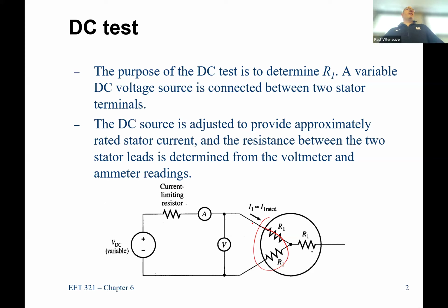We take our DC voltage, divide it by our DC current, and then we get a resistance. We divide that number by 2, and that gives us each of these individual resistors here. If it's delta connected, we've got to do a little more work, right? Because now we have that series parallel combination. So you have R1 in parallel with half of, in series with half of R1.